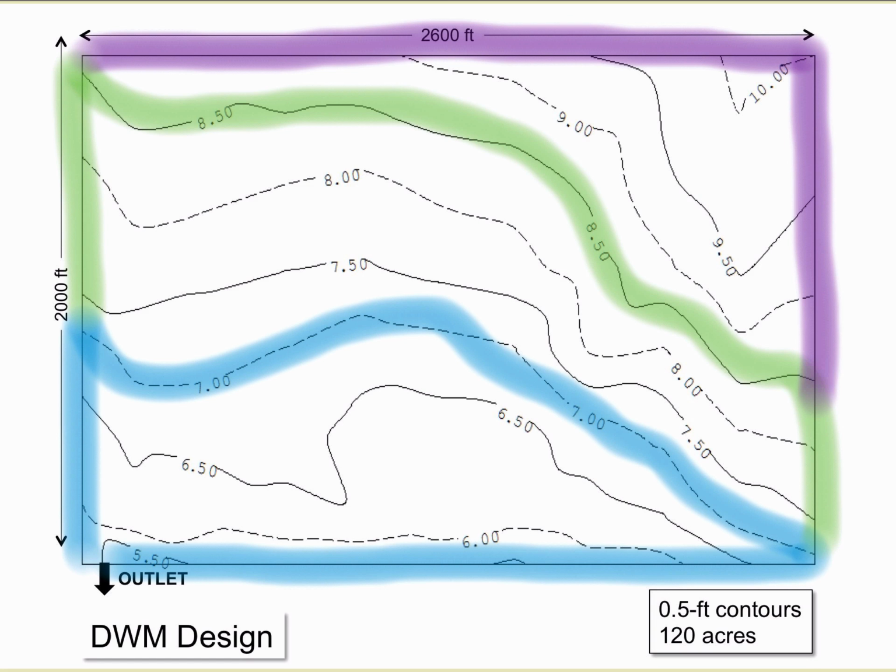Now I've got to decide where I'd like to place structures, and where the main will go, and then where the laterals will go. For the first scenario, I like to start simple and just put in a main along the west side of the field over here.